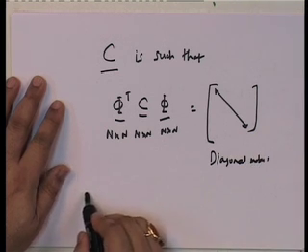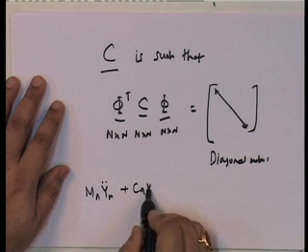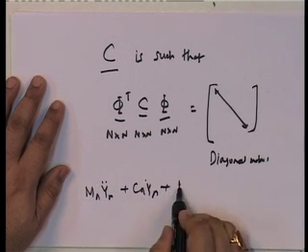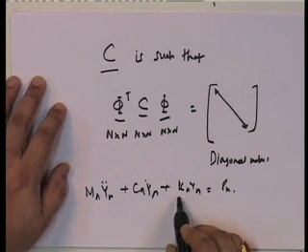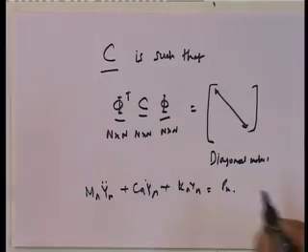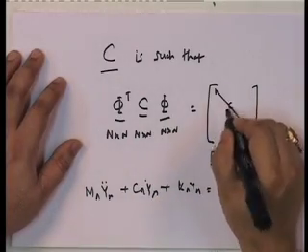So that we get M_n q double dot plus C_n q dot plus K_n q is equal to P_n. Note that K_n is equal to omega_n squared M_n. So, it is the same thing, and the C_n is this one.